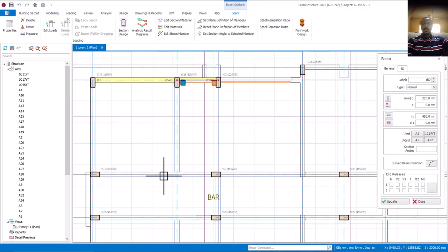You can see there's a what? This wall. Where is it? Okay, can you see what we have here? And since we are having this one here, we are going to be having another beam here. We cannot just run a cantilever from here like this, standing alone. That's the ability to think now. We must have a beam that will connect from here to this place so that we'll be able to have this beam running. Is that okay?